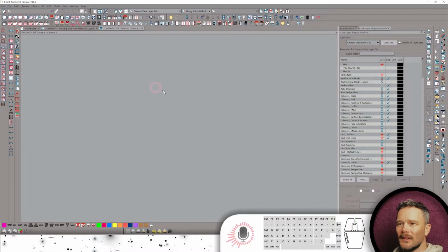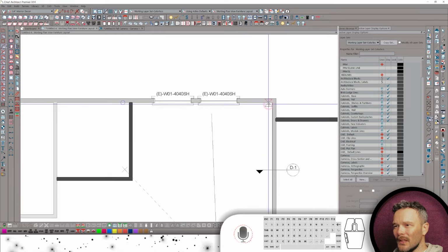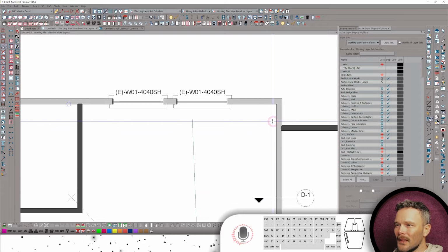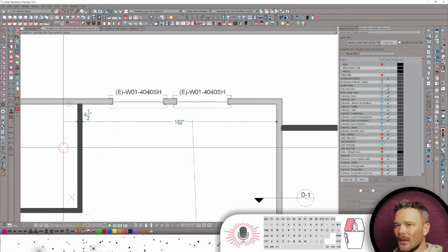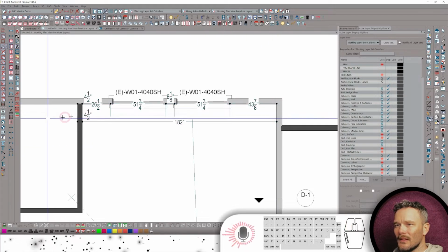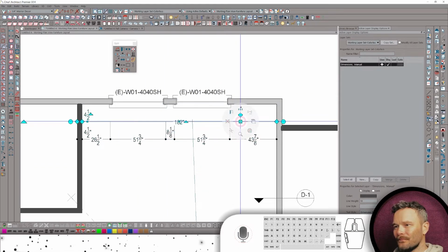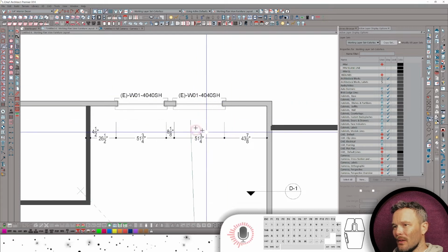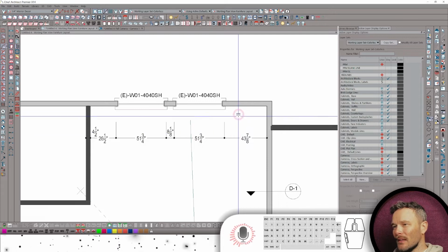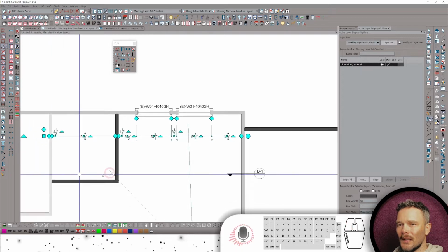And then if we get back into our saved plan view where we've got furniture here, and I want to get into that manual dimension tool, my manual dimension tools are very precise, which means that they will not pick up things that are too far away. So that if I draw it out here, it's only going to pick up those walls, okay? But if I draw it in tight next to those windows, look, it picks up that window casing because we're in the interior working plan. So there we go. It'll show that window casings dimensions. It's very precise. I like to do a tab or enter input to get my offset for those dimensions. And of course, you can do that continue on to carry through.